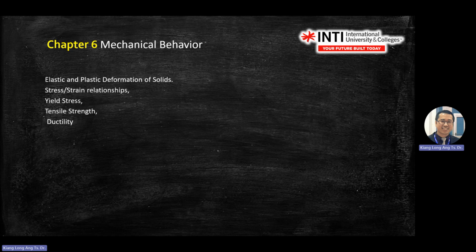This force will give you two things: normal stress and shear stress. Both use different formulas. For normal stress, you use Fy divided by area.